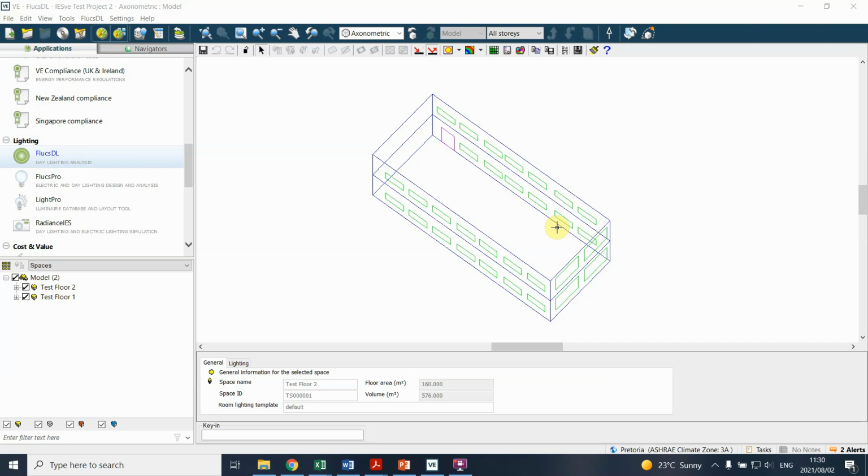What that points out, though, is certainly you have to look into the implications of overshadowing that takes place. And I haven't done detailed analysis of that yet, but you can model surrounding buildings and see whether that actually adjusts the indoor light quality, which makes sense. It should, if you want to represent reality. So something to just consider. But like I said, you must have the geometry ready. It must be located. I'm using the model that we have been using, so you'll see that it is correctly located, and we've got the geometry we're using.